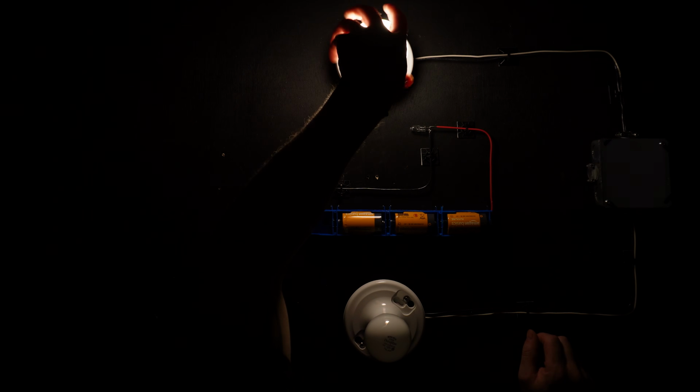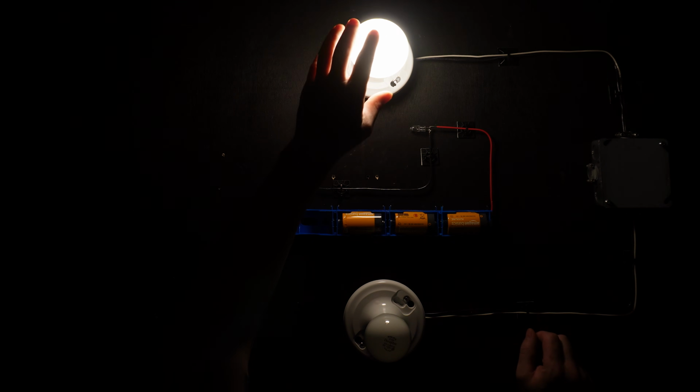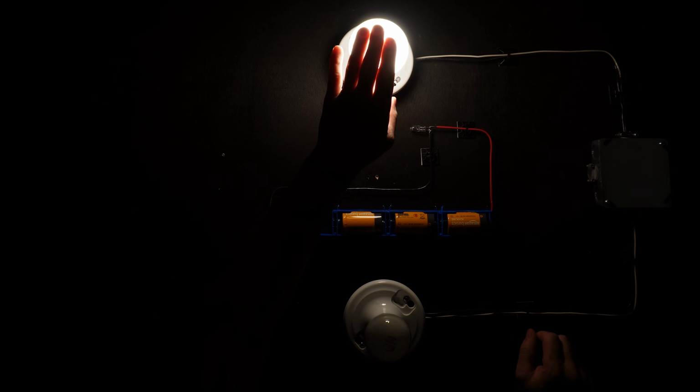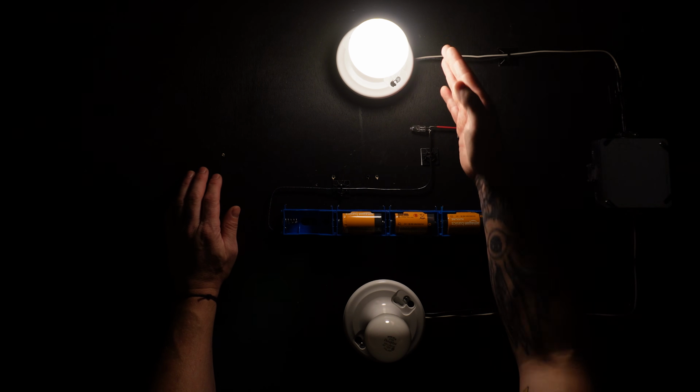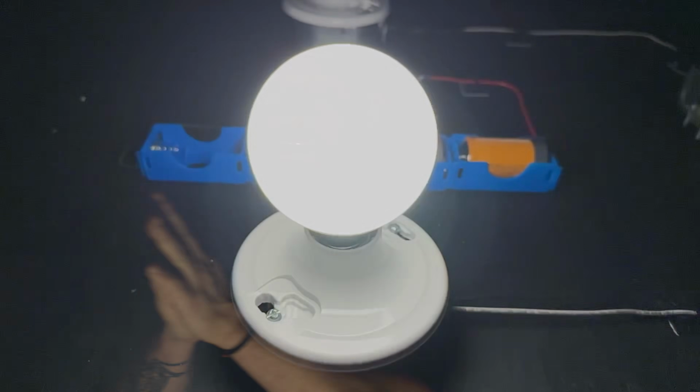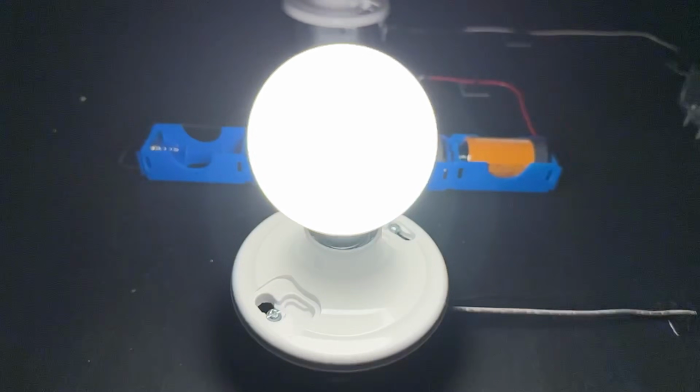Now we're going to put this LED bulb in, which LED is again just a diode. It only allows current to go through one direction. That's what a diode does. So what we're doing is taking 120 volts in, that's AC power, and converting it to DC through a diode and then rectifying it so that we have a pulsing that's in one direction rather than alternating directions. It's just going in one direction, stopping, then going in that same direction, then stopping over and over and over. So even though we are DC, we still notice the pulsing effect on the bulb because it's a pulsing DC. It is not a clean battery powered constant DC.